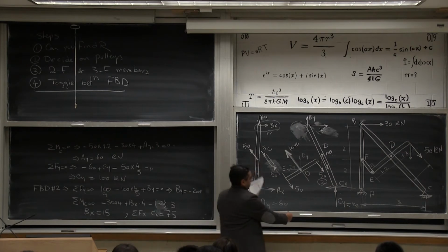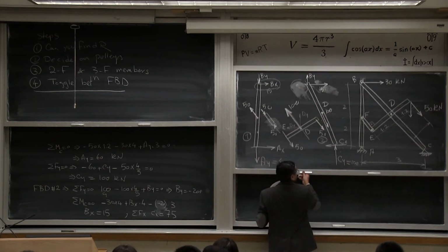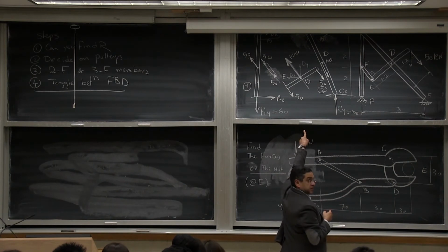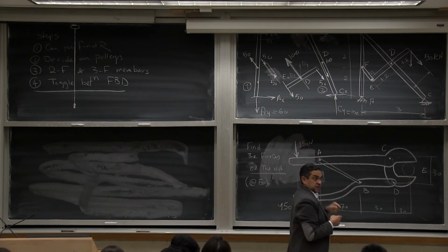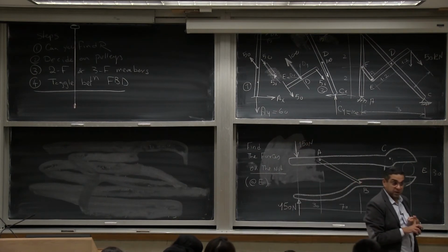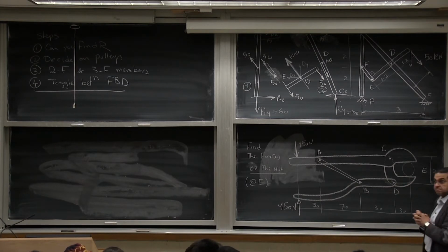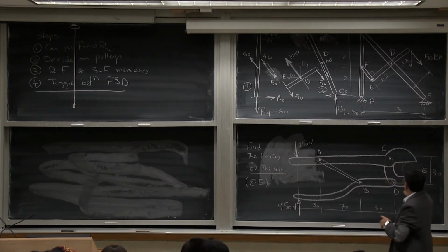Okay, I have another tough example, and then an easy one. Member in the middle is a 3-force member. And a 3-force member has to be in equilibrium. That means two things. Either all forces are parallel, or all forces meet at one point. And in our case, all forces were parallel, and I divided them 50-50, 100. Where's point E? Point E is this.